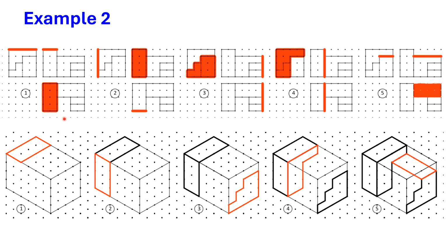Now you consider any one of the planes, because I will be starting from the top view. So the top view, this plane I consider. This surface in the top view is appearing in the front view here. The same surface in the side view is appearing over here. So this surface is a principal surface, and that is on the top view. So you will be drawing the top view here.